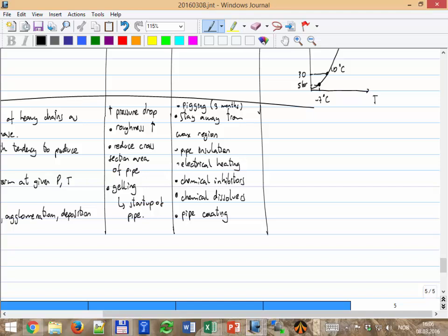We have erosion due to sand, due to bubbles, due to droplets. The typical case is that it's impinging on the walls and making holes, and what's happening with the coating? It goes away. So if you're relying all of your protection against waxes on a coating, and then the coating goes away, you're not protected anymore.